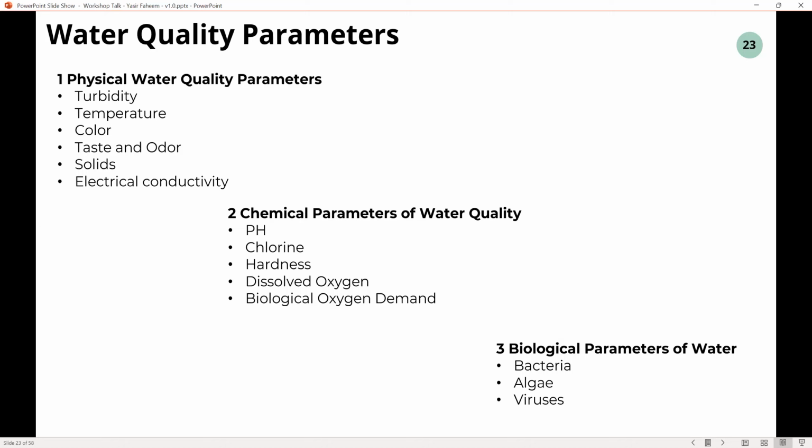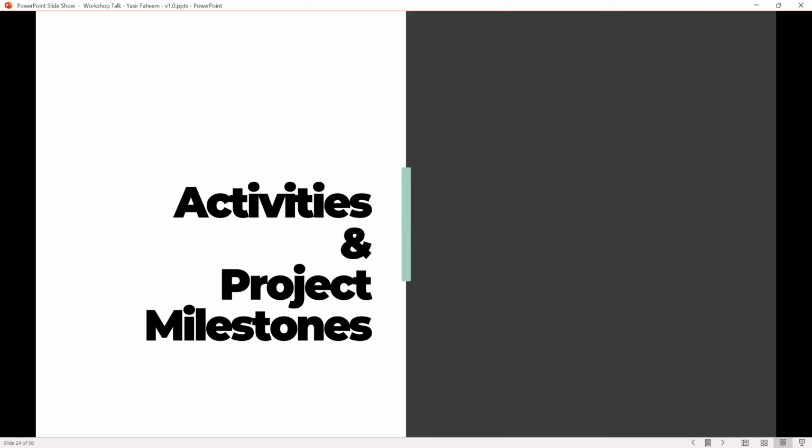High temperature causes increase in contamination and decomposition of organic material, which results in increasing consumption of this oxygen. Also, at the same time, the amount of ammonia released due to that degradation and released by fish gills increases. Ultimately, that overall environment becomes contaminated even for the aquatic life. Okay? So if they can die, we are definitely going to be infected if we consume that product.